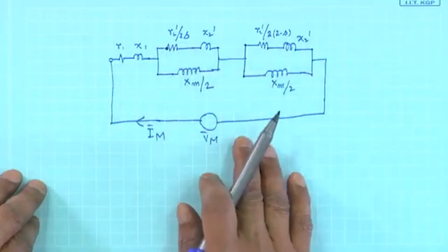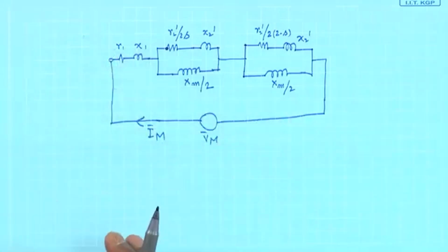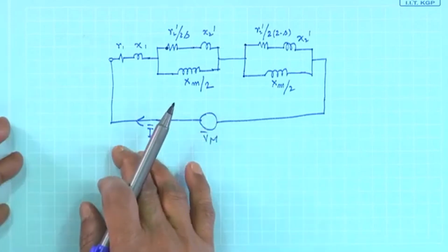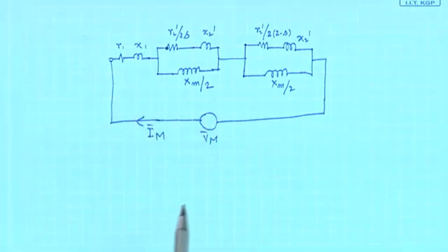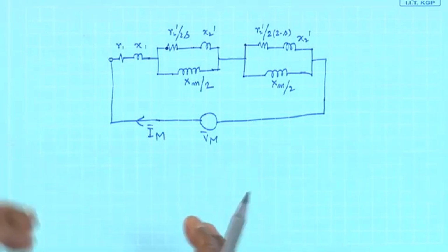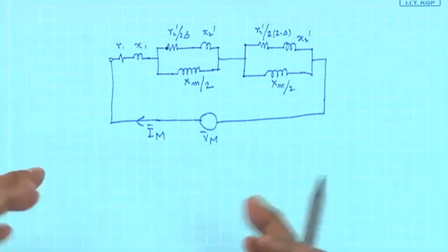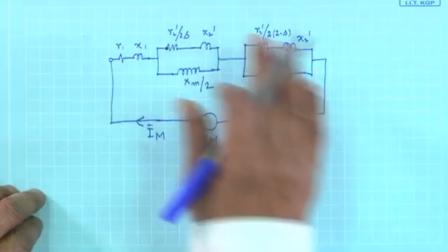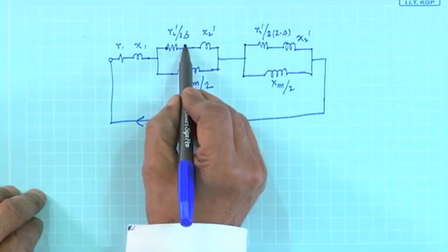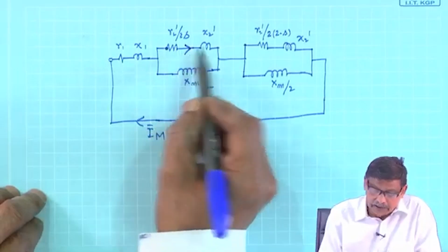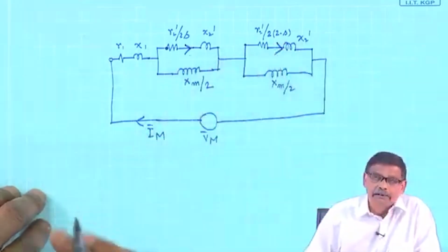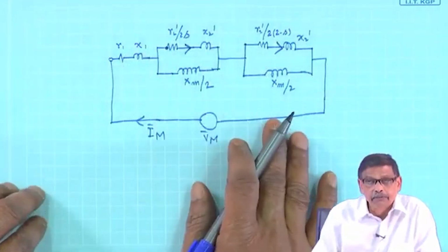Welcome. So, this is the final equivalent circuit of the induction motor that we have derived, and I am now happy. I have applied voltage V bar m, the current drawn is I bar m, which I can determine experimentally, and it has a meaning. No question of positive sequence, negative sequence, those things I have taken into account already. And then considering this, calculate this current, whatever it is, and calculate this current, whatever it will be. After that it is a circuit problem.